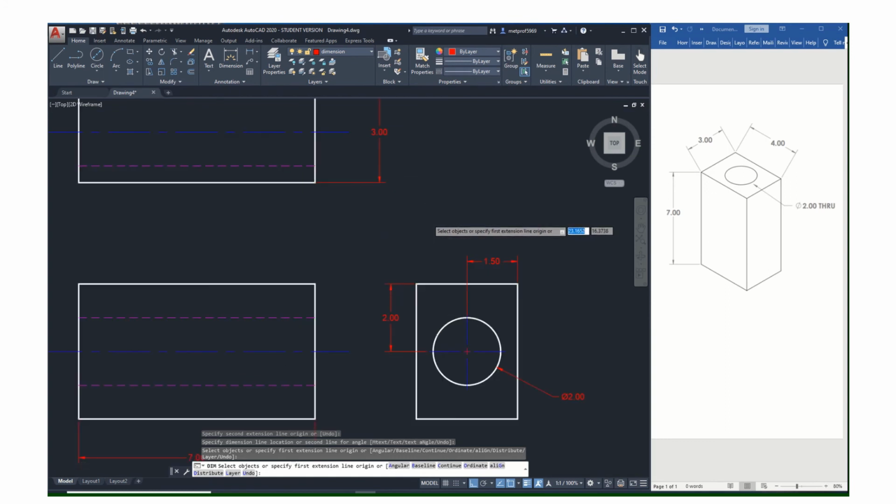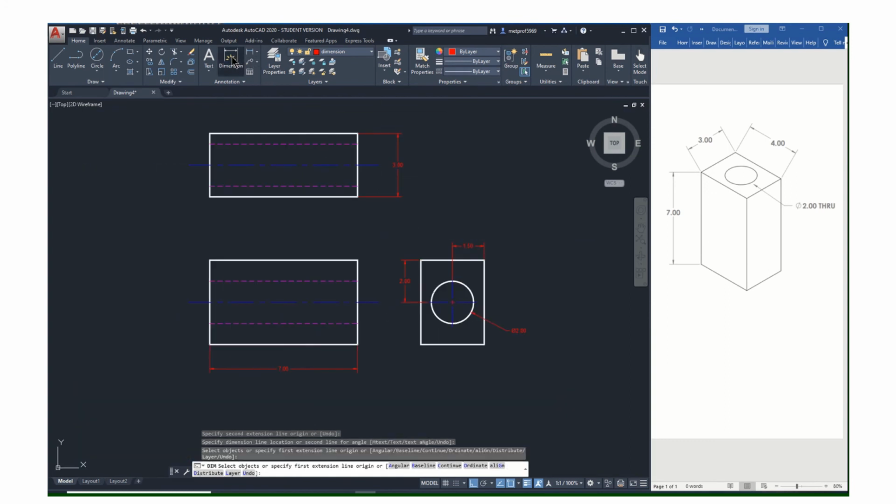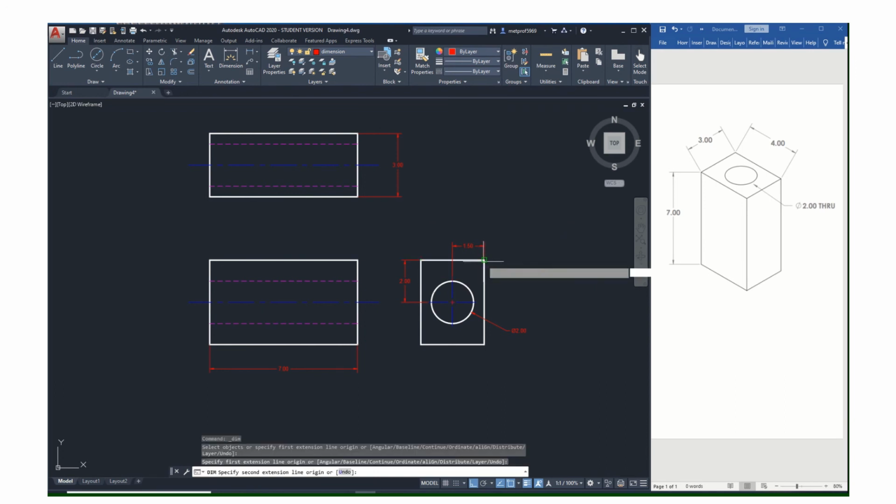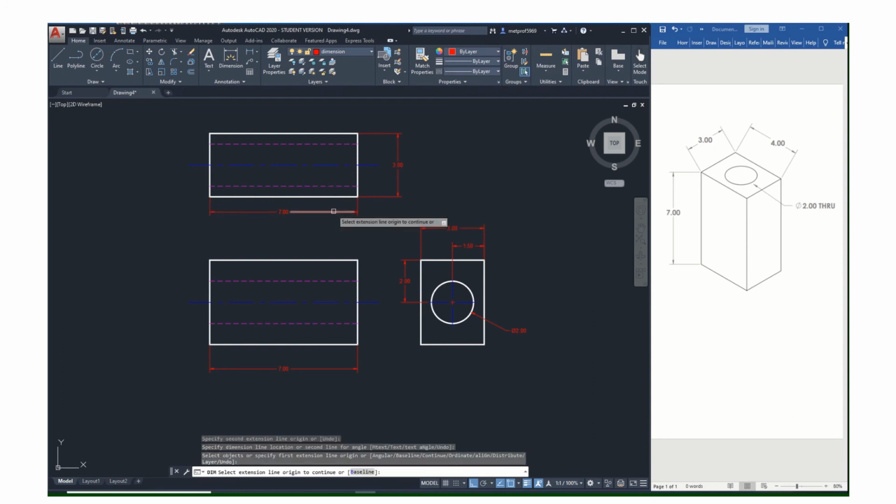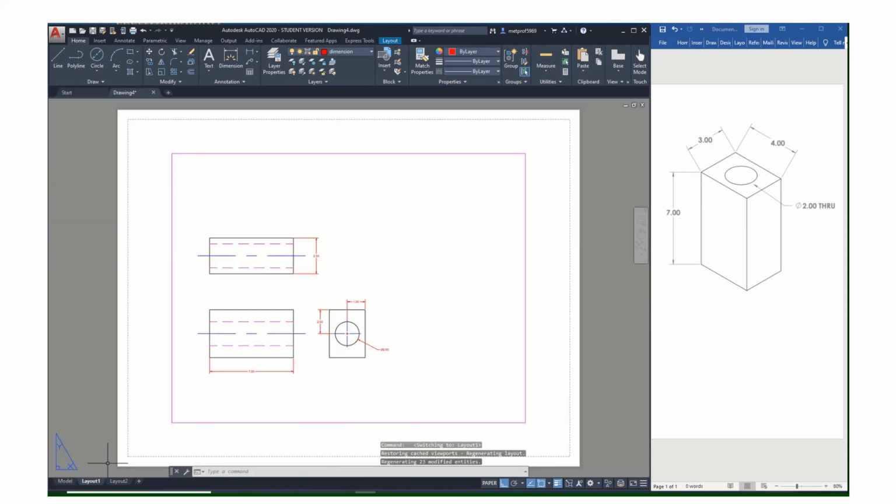Rule of thumb is don't double dimension. There's no point of me dimensioning this twice. Just doesn't make sense. Again, that's one of the reasons we line these up. So double dimension creates more confusion. Now, sometimes if you have a really complicated part, certainly feel free to add extra dimensions to help with clarification, but don't put dimensions on it just to have something to fill up the space. This is a simple part. It'll get much harder and you'll need the space for more dimensions.